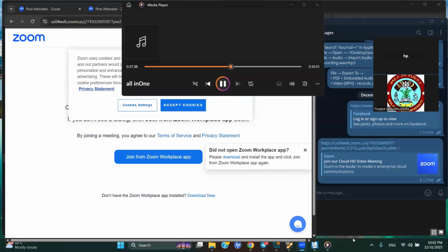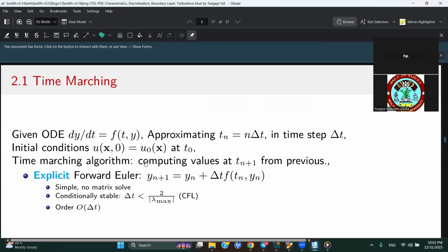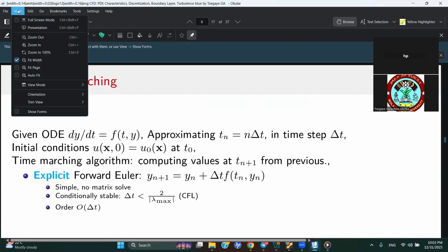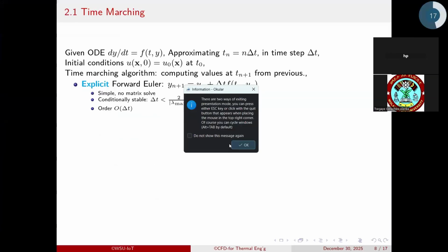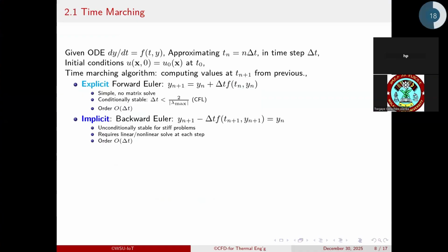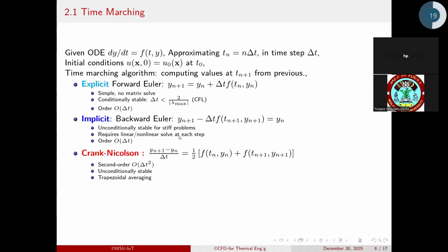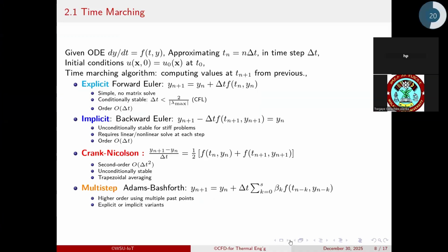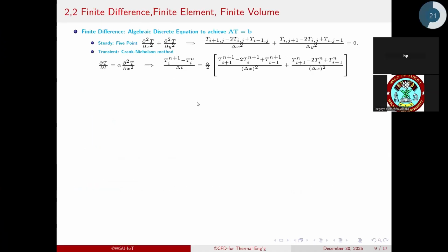And discretizing a governing equation involving transient terms, the unsteady phenomena, the current or future conditions of temperature or pressure at n+1 are approximated from the previous, as in the illustration from 1 to 2, using a technique called time march. Finite difference method.